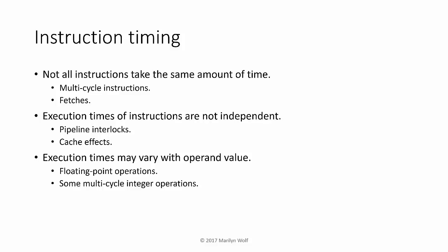Furthermore, the execution times of instructions are not independent. Pipeline interlocks and cache effects mean that the execution time of one instruction depends upon the instructions around it. Execution times can also vary with operand value. For example, floating point operations may take a longer amount of time, in particular division and transcendental functions. We may also have some multi-cycle integer operations.